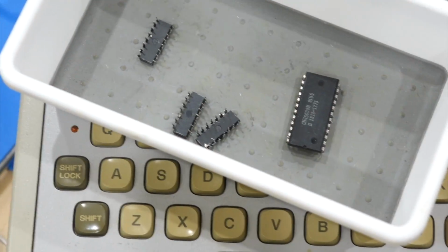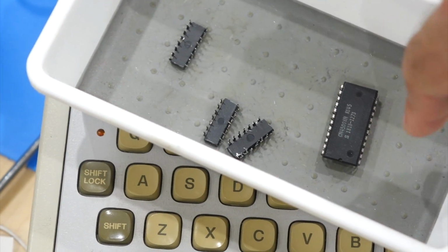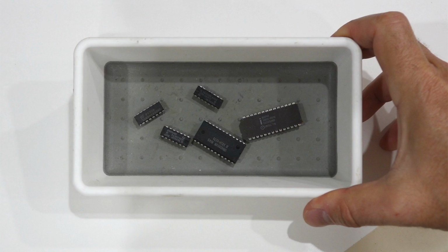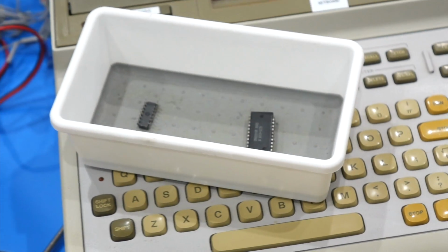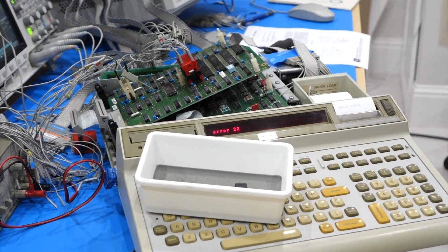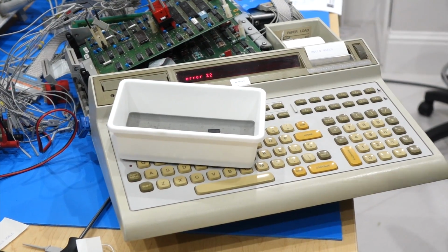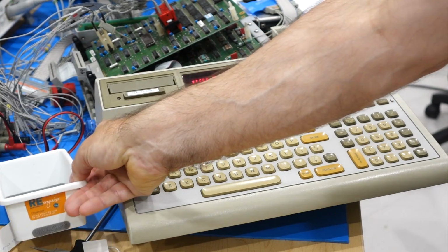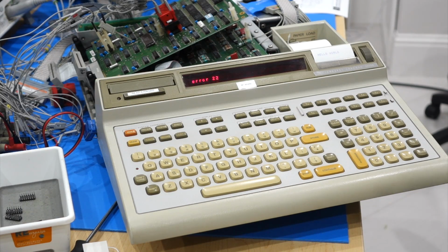And they were 4 chips, actually 5 chips, because Ken took the Intel one. So 3 TTL, the Intel controller, and a ROM that went bad. And I suspect that ratio is to keep constant. We probably have about the same number of bad chips on the A25 board, which we would need to bring this back to a T level. Also on the processor board we had 0 chips failed, so we'll see where that goes, but it's encouraging.